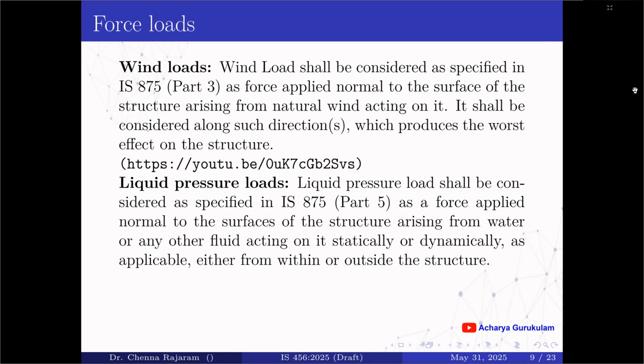Liquid pressure load shall be considered as specified in IS 875 Part 5 as a force applied normal to the surface of the structure arising from water or any other fluid acting on it statically or dynamically, as applicable, either from within or outside of the structure.